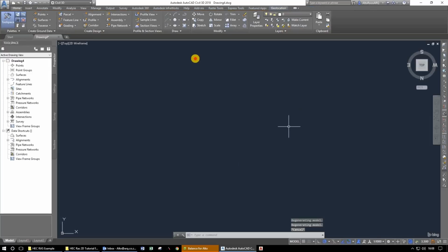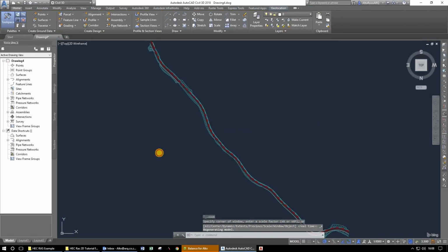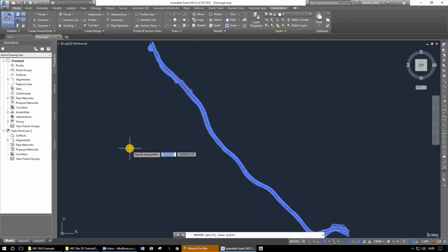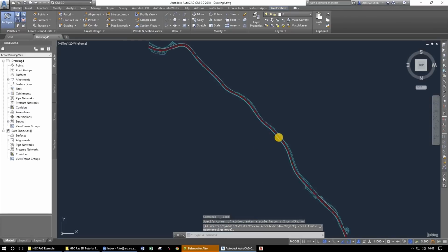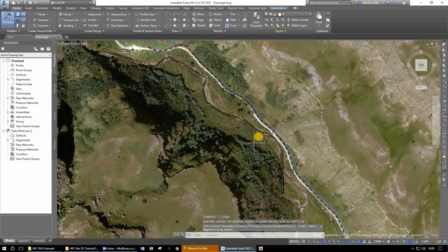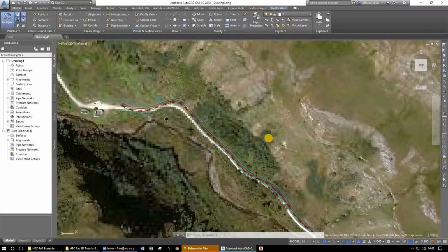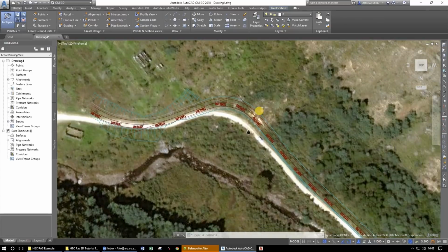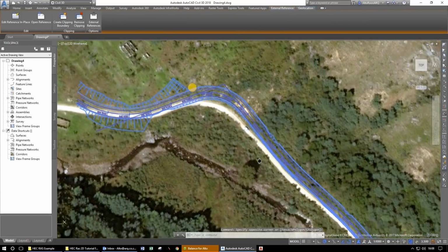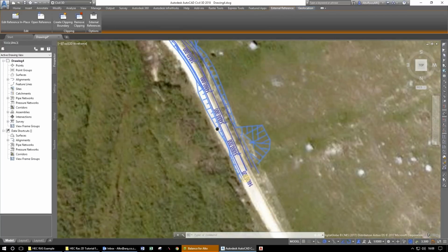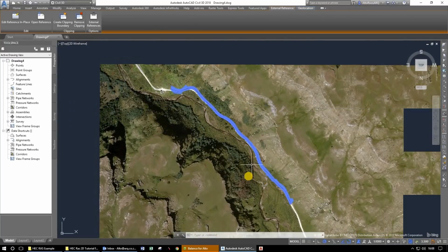Anyway, what we need to do is rotate our XREF by 180 degrees so that it falls within the correct position. That's just a rotate from 0,0 where we inserted it, 180 degrees, and now, as you guys can see, it is on the image at least. If we zoom in on this, the XREF is the plan for the new road that they will be constructing, and as you guys can see, it relatively lines up with the image that we've got.